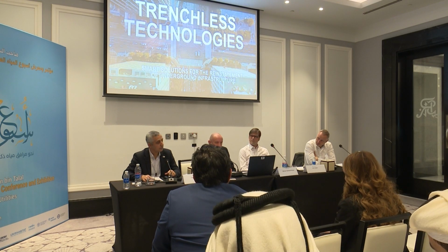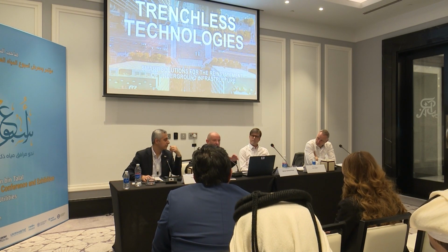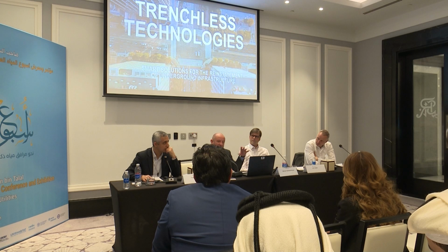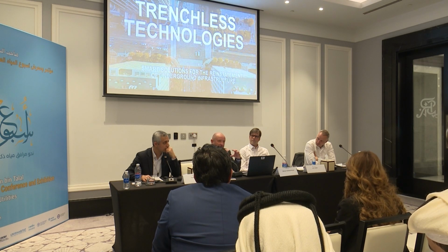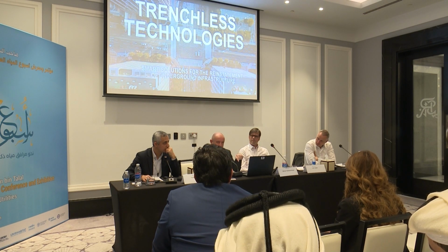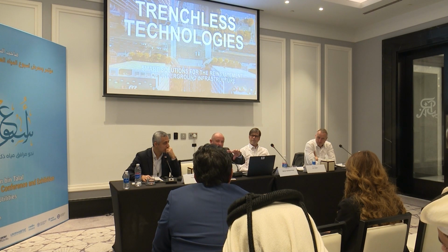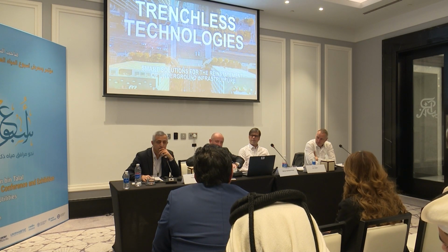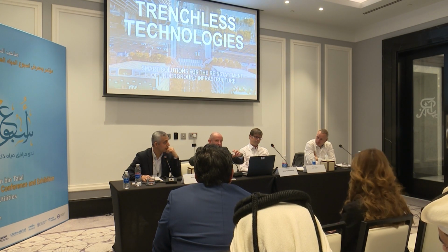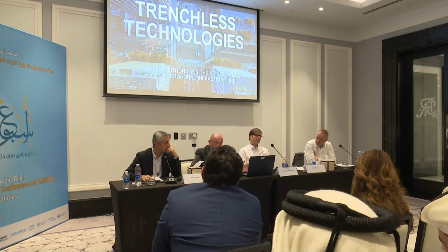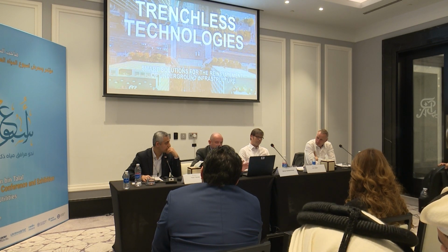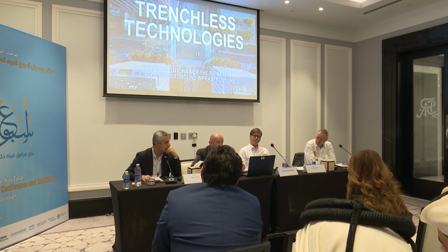And what they do now, when they make a new construction, they do a very simple, cheap concrete pipe, even no socket, just in the ground, and line it from day one with GRP UV liner to have the earthquake protection, because the liner is stable, but it's not brittle. And it's overcoming, let's say, movements of the earth. There's a program, this is obligatory in Japan, that this can be only lined after this Japanese standard. I have a copy, it's in Japanese.